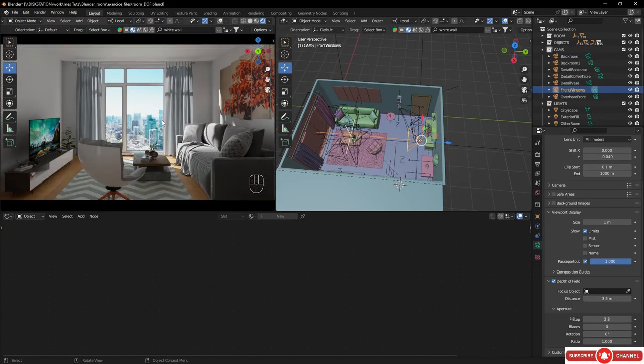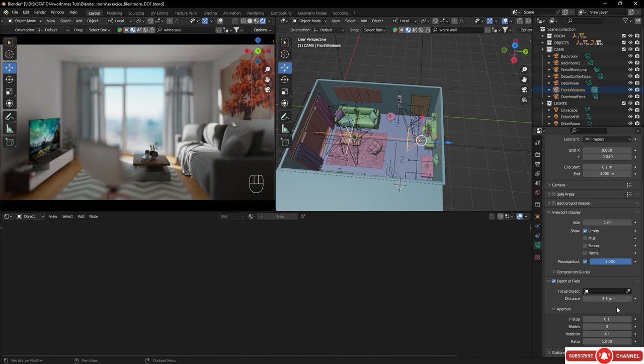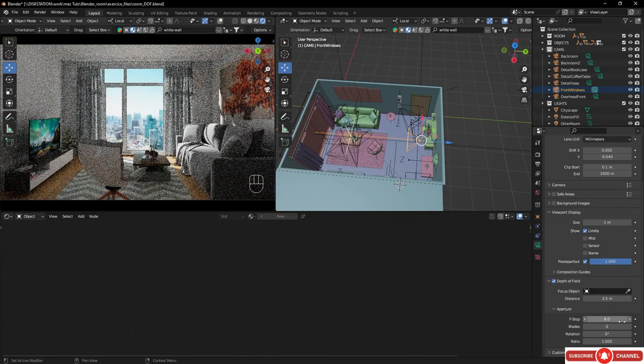So it's activated. And as you can see, if I put it with a very shallow depth of field, it works, and it does give us a very strange feeling, like it's a small scale object of everything. Instead, we're going to change the f-stop to 8. So the background and the foreground are going to be very slightly blurred. We could even try maybe 4 again.